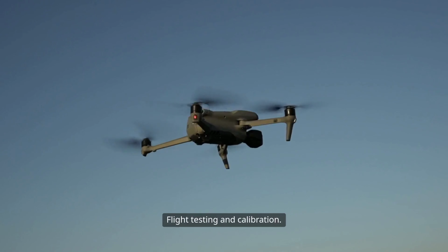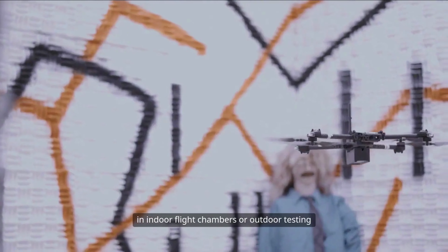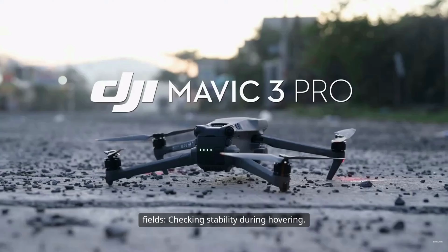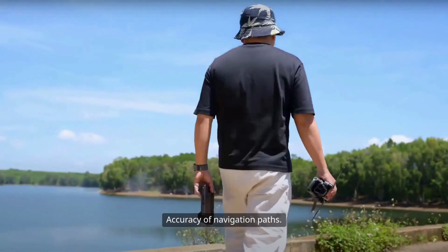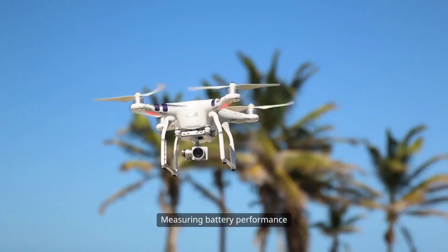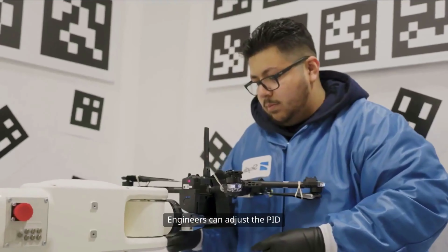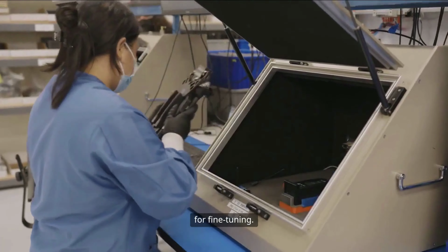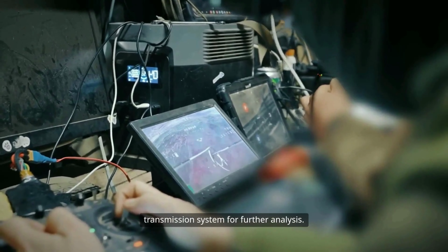11. Flight testing and calibration. This is an important stage that takes place in indoor flight chambers or outdoor testing fields, checking stability during hovering, maintaining altitude and GPS lock, accuracy of navigation paths, obstacle avoidance and emergency safety systems, and measuring battery performance and flight time. Engineers can adjust the PID control loop, proportional integral derivative, for fine-tuning. Data is collected through a remote data transmission system for further analysis.